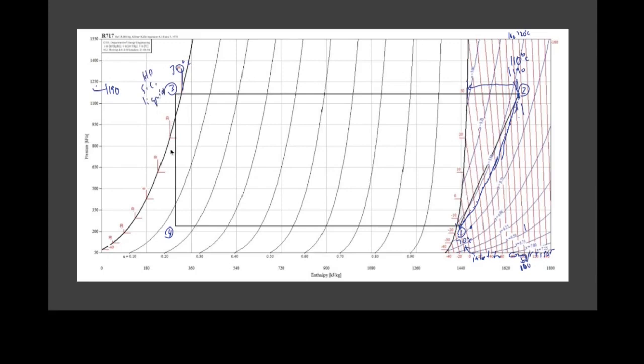And we are going to now put that into the evaporator, and we're going to control its flow using a metering device, a metering valve. Maybe it's an expansion valve. Maybe it's an orifice plate. Maybe it's a capillary tube. Maybe it's a float control, a high side or low side float. So this is where our metering device is. Across the metering device, we've got a delta P, and that delta P drives the liquid refrigerant through and into the evaporator.